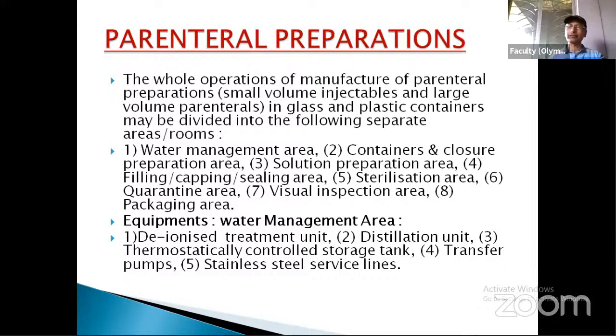if your water pipeline is not properly made with proper quality of stainless steel, so you have to see that you prepare proper distilled water. You have to maintain it at 70 degrees centigrade temperature all through, during the transit through the pipelines, supply lines, and while keeping it in the storage tank. Everywhere its temperature should be not less than 70 degrees centigrade, such that microbial growth can be avoided.